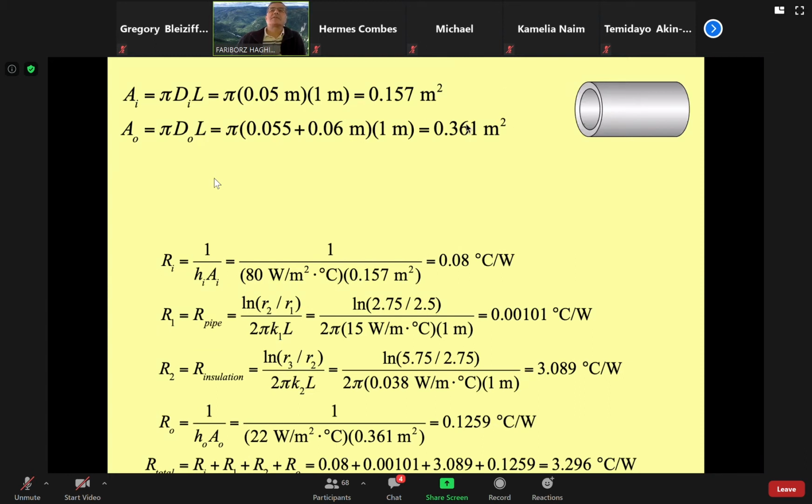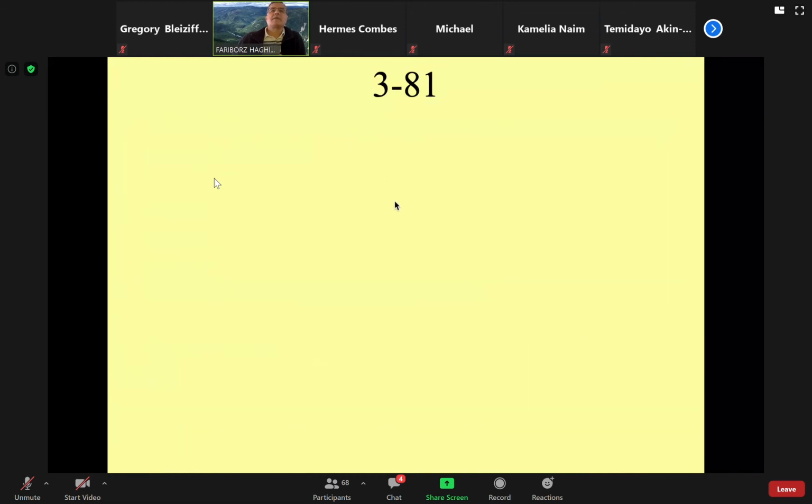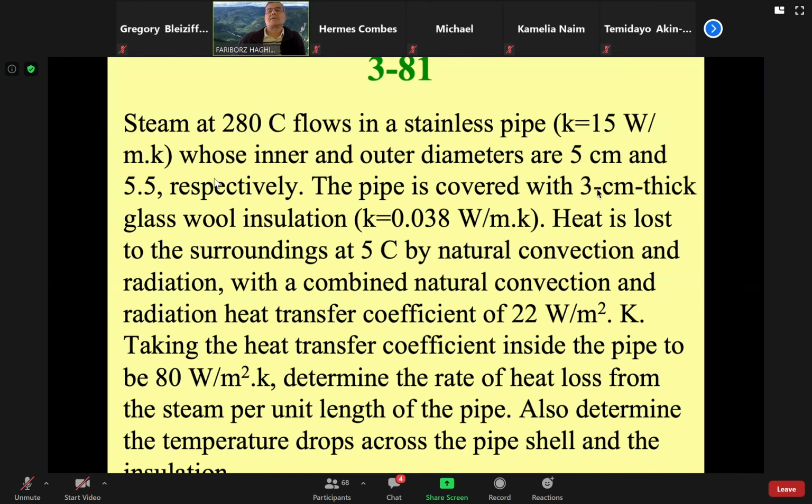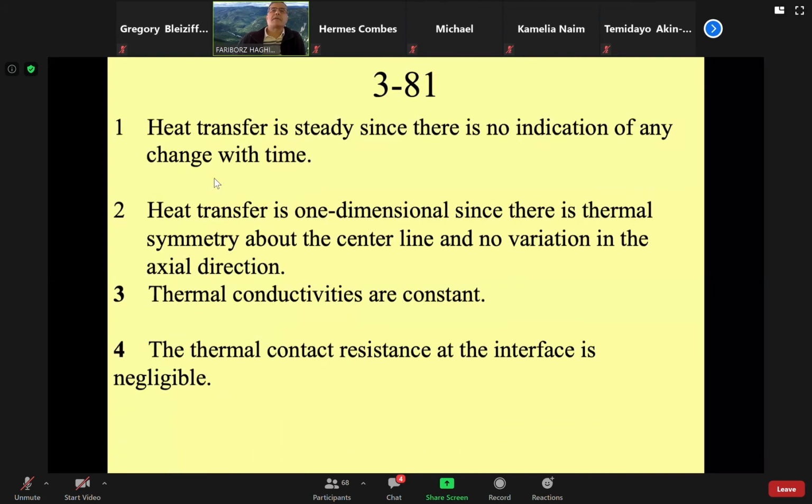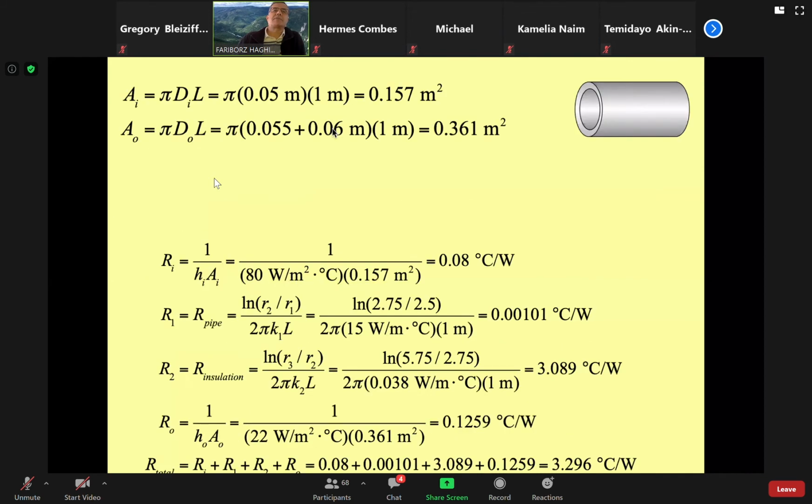Therefore, that's why 6. If we are wondering why, here we mentioned 3 centimeter, and if you look at both sides of the pipe, that becomes 6. It is 3 centimeter this side and 3 centimeter this side, so the diameter becomes the diameter of the pipe plus twice the thickness of insulation, 0.3 centimeter here, 3 centimeter here. This gave you that one here.